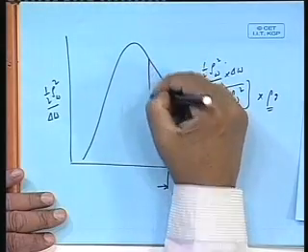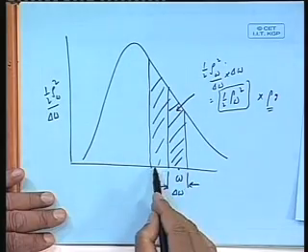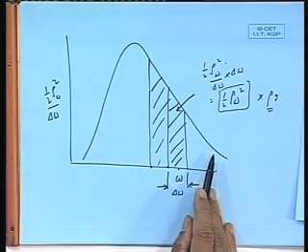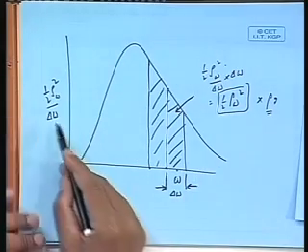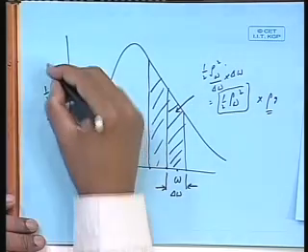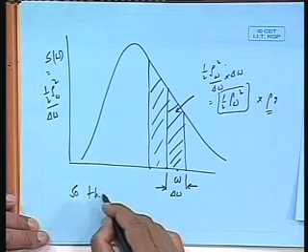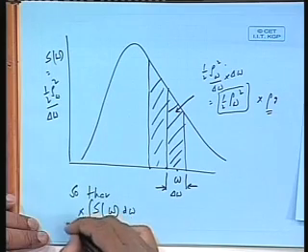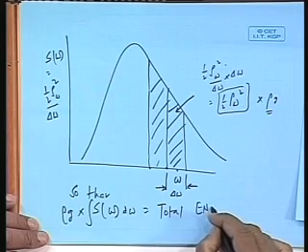Now, supposing I take this frequency band here, what is this area? This area is the energy of all the waves in this frequency band. Like that, if you keep on adding, the entire area under the graph will represent the total energy of the water surface. This is why you have this coming here, or I can call this S omega, so that the integration of S omega d omega into rho g gives you the total energy.